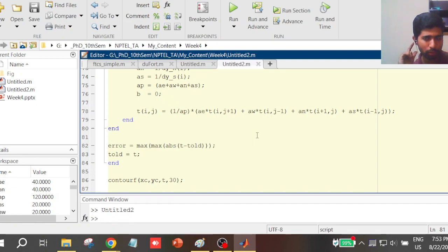The reason we use central approximation is that it is more stable. If you see the upwinding schemes, especially the QUICK scheme, which I have used also, QUICK is very unstable, although it is more accurate. But accuracy is one thing and stability is another. These are not very stable schemes. And definitely we get physical results with central approximation also.